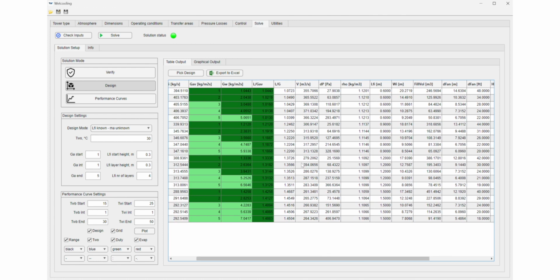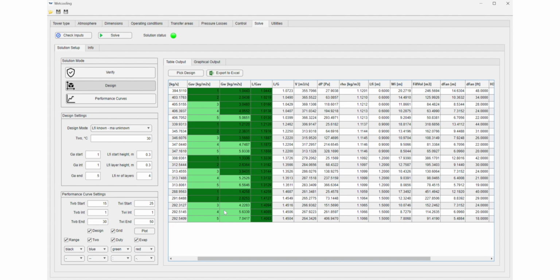And the most important step here is then the specification of the fan. And generally, when you specify a fan, the fan curves available, it's the pressure drop that you have to specify, or that you have to know, the volume flow rate in cubic meters per second, and it also gives you the density of the air at that point. So using the volume flow rate and the pressure drop, you can then find a fan and specify a fan that will give you that duty.